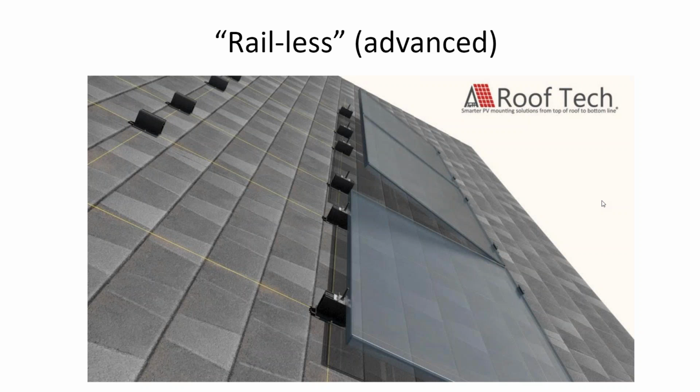Solar panels are big and flexible rectangles, and the rooftops are wavy, so they're very hard to square to begin with. And that rail is helpful because if you get the rail square, then the panels will go on square.